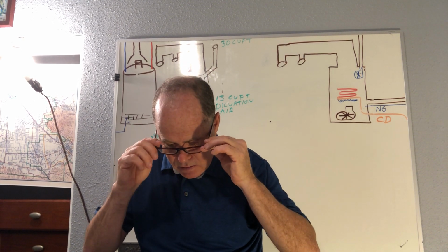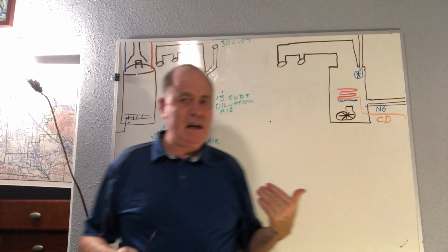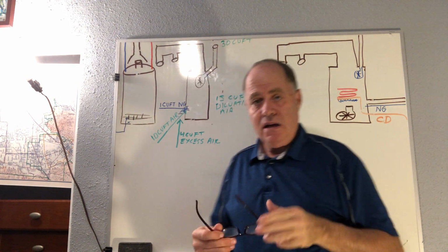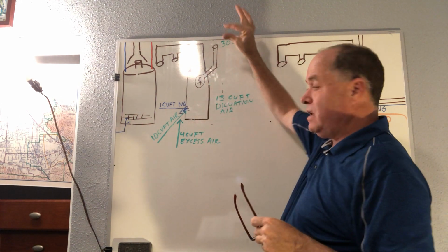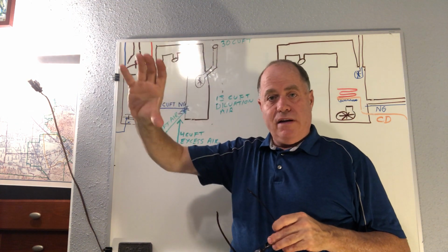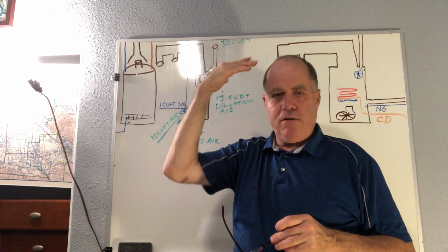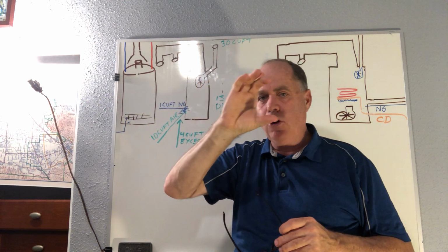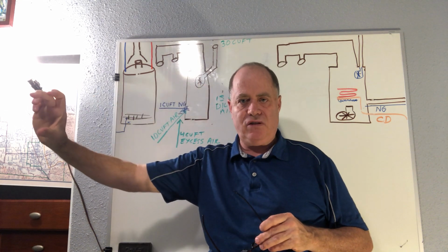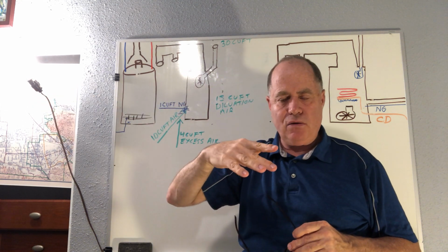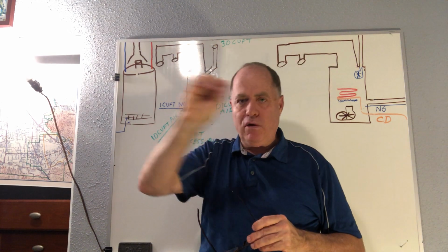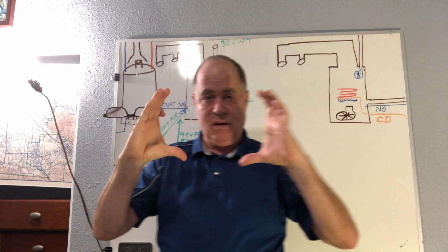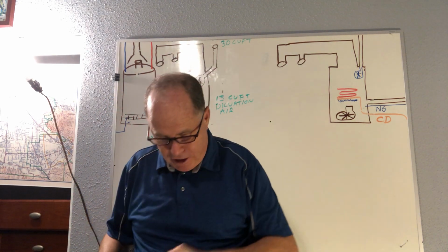Okay. Now, if you are providing air for any space, you have to have a certain amount of openings, okay? And what they're saying is that for a garage or anywhere that you say, well, we have fresh air coming in here, and I'm just going to have a little tiny slit, no, whatever opening you have has to be at least 3 inches so that nothing can block that, okay? You can't just have a tiny crack that goes the whole distance of a building or something. It's got to be at least 3 inches so that you can actually have like a vent, okay?